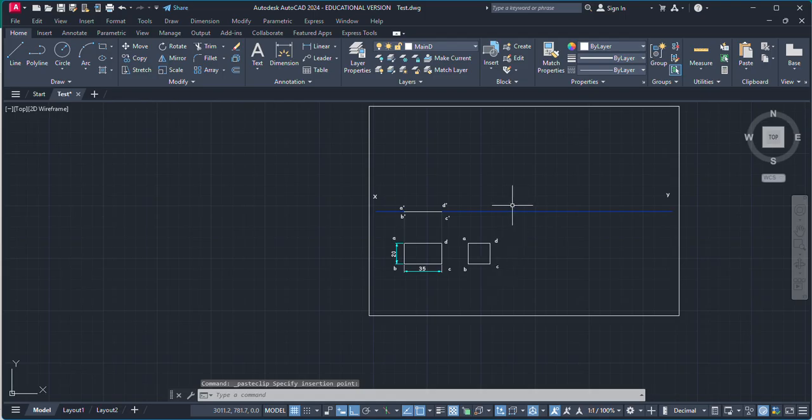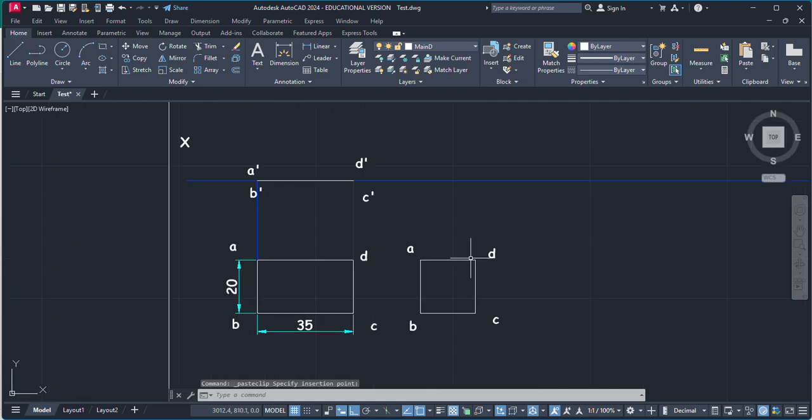So now we need to find the angle. What should be the angle, so that after getting inclined at that angle, we are getting the square in the top view. So just do one thing. This is the resting corner, resting edge. So it should stay on the reference line. So this point A dash B dash should be this one. This point represents this one because this is the resting edge.